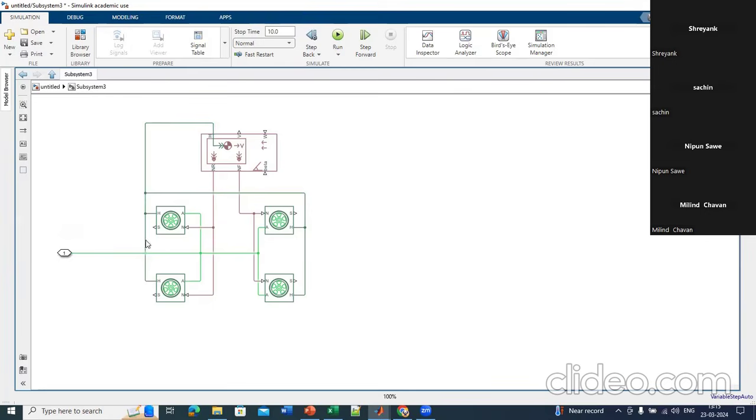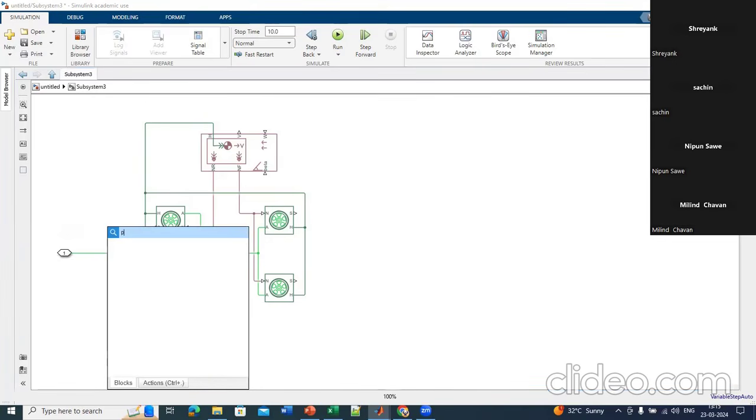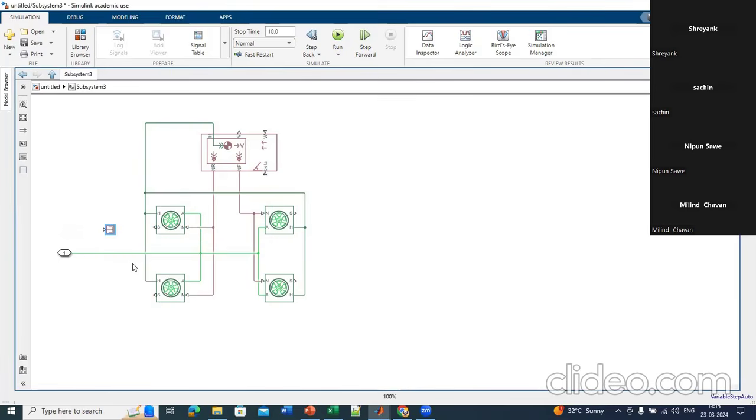Now what we need to do, this S port we don't actually need. We can terminate this using a terminator block, PS terminator. Let me rotate this. Let me copy here. Let me copy here. Let me also copy here. Okay, let me rotate this to this one. So S connected. Here also S connected. Here also S is connected. And here also AC is connected. Okay.